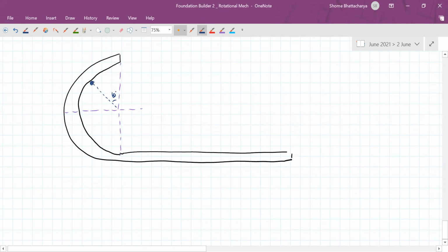So this is where it loses contact. Now when it loses contact, its speed was, remember, V prime. So it goes in a path like this. This V prime will be at the same angle to the vertical. This angle is 90, so this angle will also be 60.